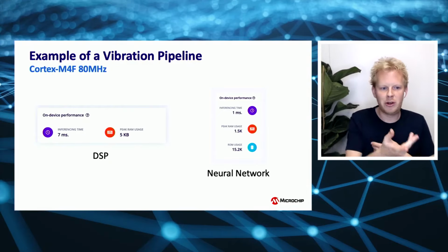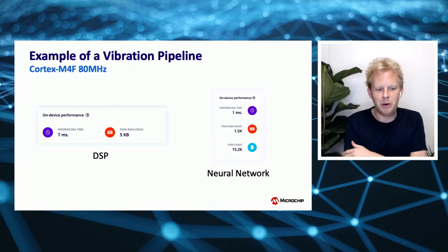And that is efficient. So this is on our Cortex-M4F. We can do that in about, let's say, 10 milliseconds with 5K of RAM, depending on your FFT length.